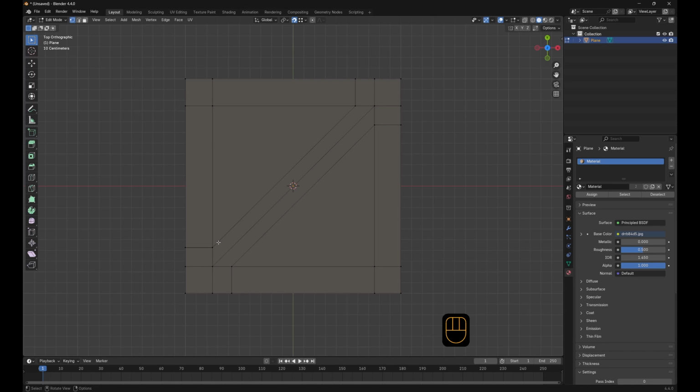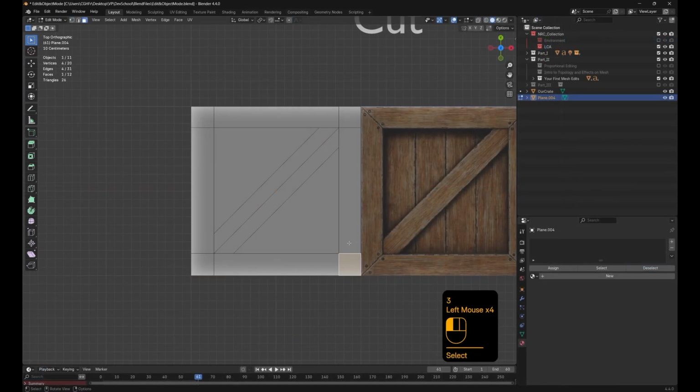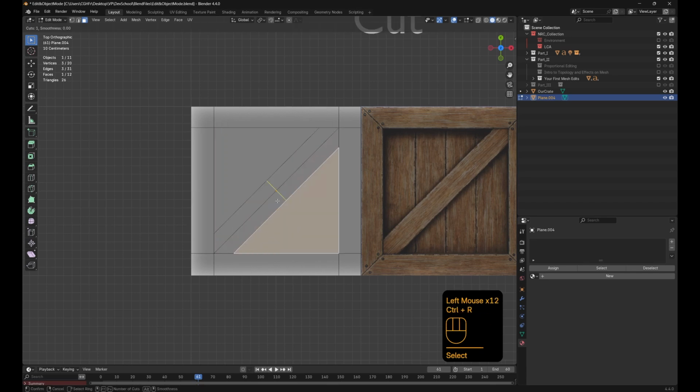That you might have got away with, but any chance if this was, say, a part of clothing, like a square of a sheet of fabric, and whilst it was being manipulated as a piece of cloth, that vertex comes over here, it will really affect that texture. You'll really see that stretch in the middle of a fabric that looks maybe perfect. A quad all the way around. We've got a tri, which is fine. Quad, quad, and tri. You'll notice that loop cuts are working, kind of, but because of these two triangles, it does still throw a few errors.